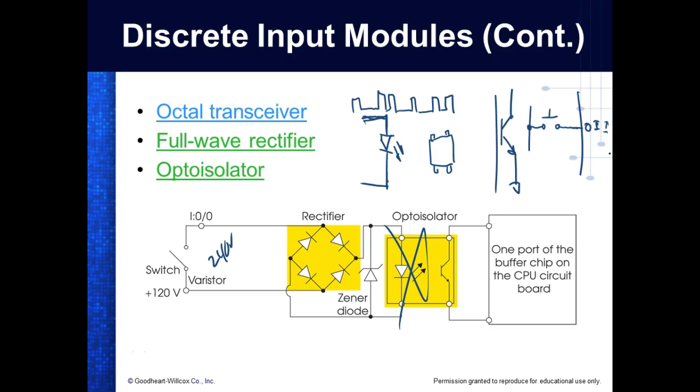Yeah, so what we're going to do is program in ladder logic, but the inputs are not connected to L1. They're not connected to the load. They're connected to an input module. And then the processor reads that input module, and then it decides what it wants to do with the outputs. So literally the PLC goes like this. I'll have an input button, then I go into an input port.